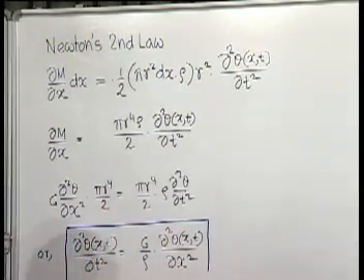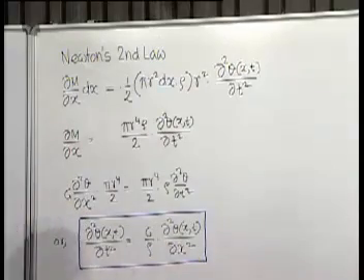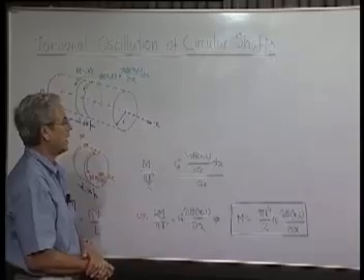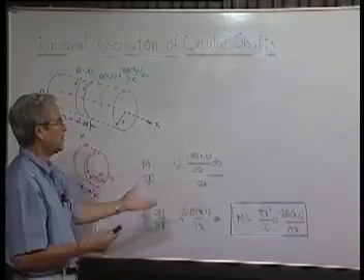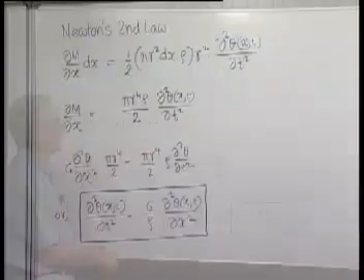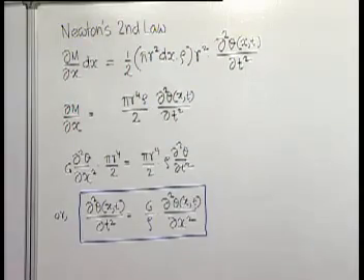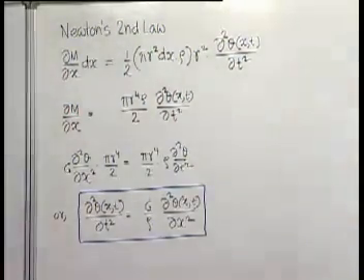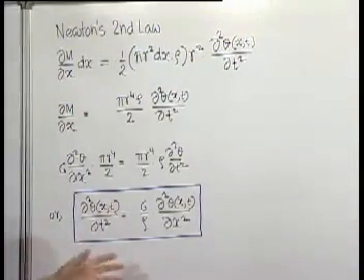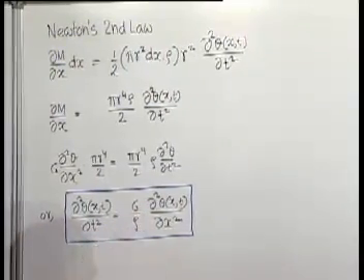This is the equation of motion which is valid, or that is the relationship between the angular rotation, time, material properties, location and so on. So this, if you remember the previous one, in case of longitudinal oscillation it was exactly the same, only here it was E by rho.